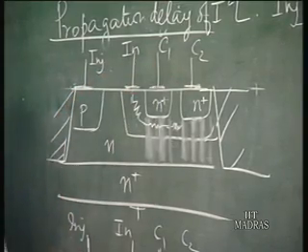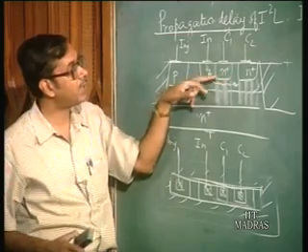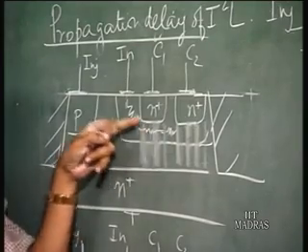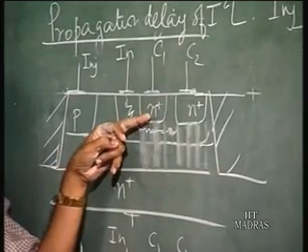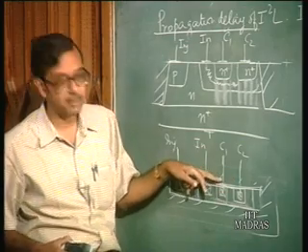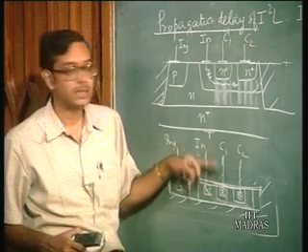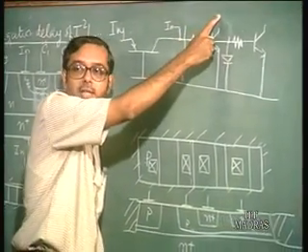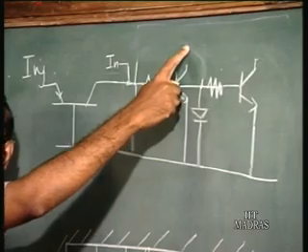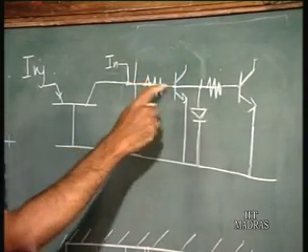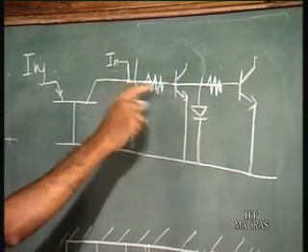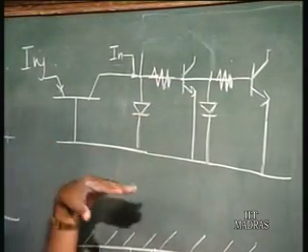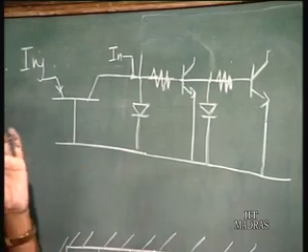If you look at the rail regions which we have eliminated, in the rail regions the current did not have to flow under any of these collector diffusions. So the rail resistance which we have removed is much less compared to these resistances, because here the current has to flow under the collector diffusion areas, where the cross sectional area is much less.